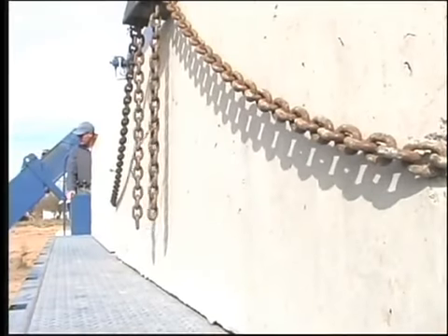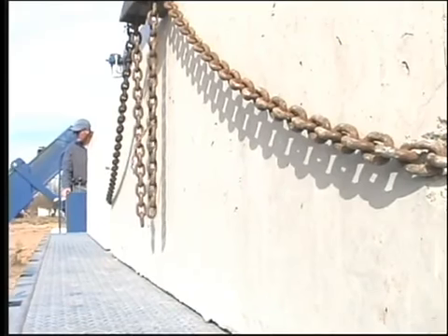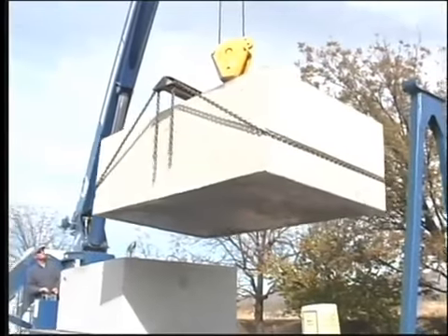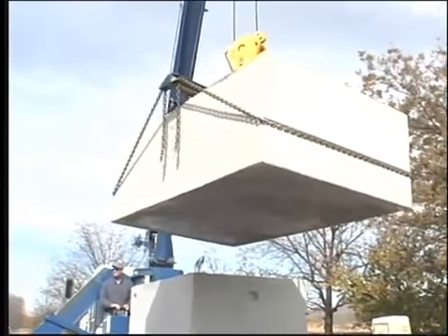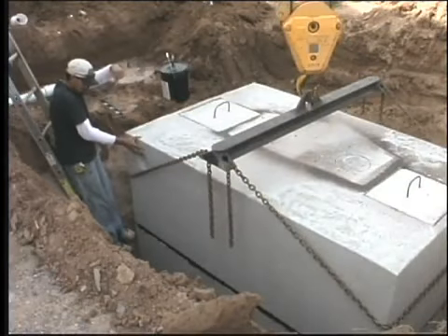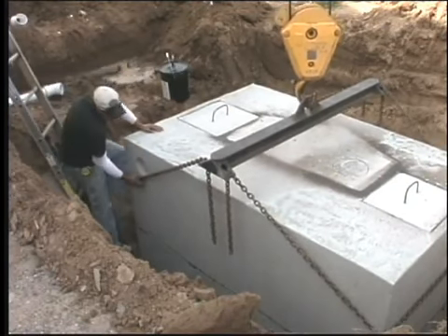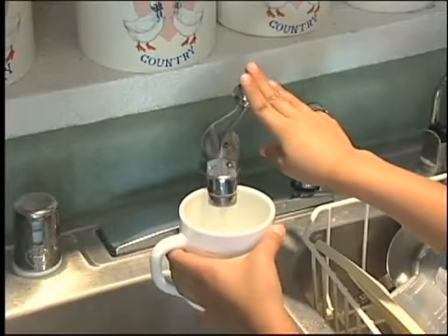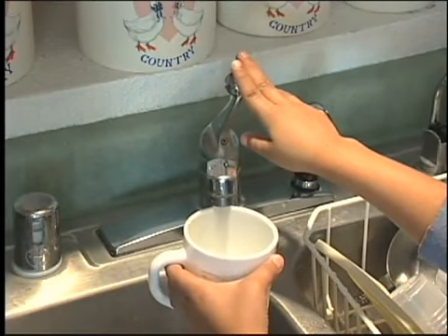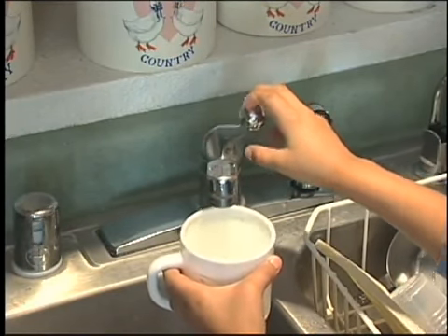Again, do not place a 5-ton reinforced concrete tank yourself. This should be left to the tank provider. You may dig the hole to reduce cost. After the septic tank is in place, inspect the tank for damage. For the protection of your drinking water, it is important that the tank be watertight.